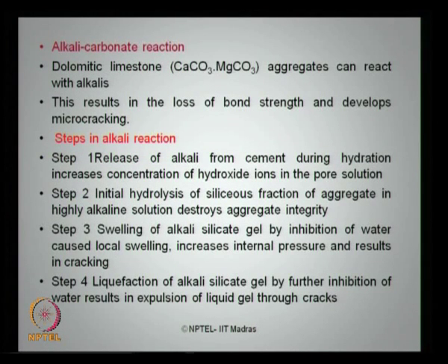If you look at the alkaline carbonate reaction present in concrete which is subjected to marine environment, the dolomitic limestone aggregates can react with alkali. This results in the loss of bond strength and develops what we call micro cracking in the concrete structure. The steps in alkali reaction can be seen as follows.